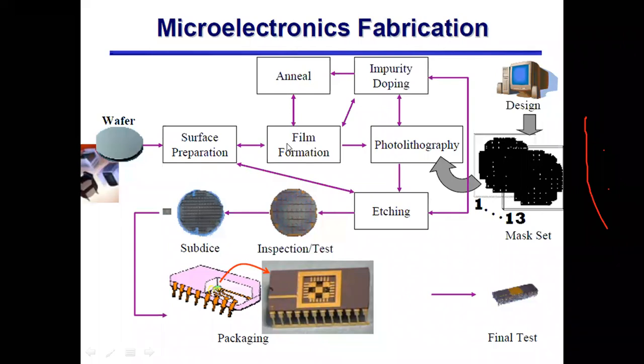Annealing, because this is a silicon wafer, it could have a different coefficient of thermal expansion, and on top of it you have added a thin film of different materials such as aluminium or gold or chromium or copper, etc. And that material has a different coefficient of thermal expansion. So normally there would be residual stresses in that deposited layer. In order to remove those residual stresses, we perform annealing.